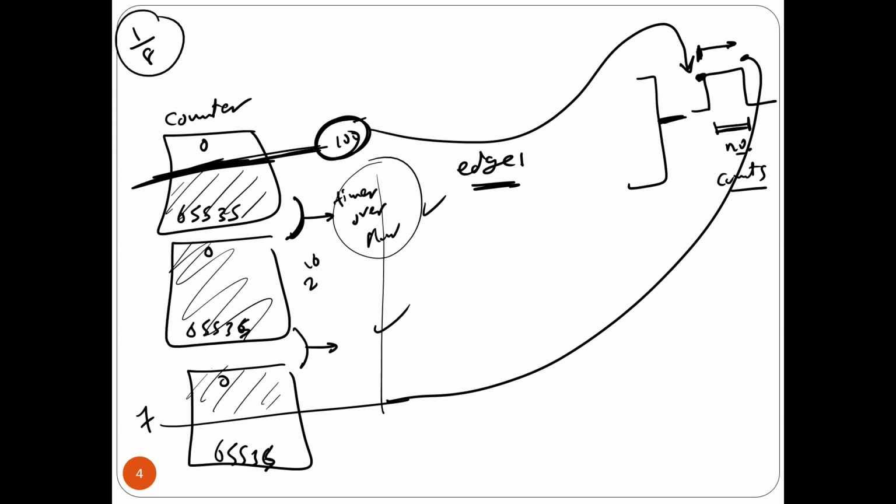That is why, as you will see right now, the timer interrupts are going to be disabled. I'm going to enable them here because I need to count overflows. How many timer overflows from here, starting from this point. Is that okay? Now, so I need 3 numbers: the beginning, the end, and how many overflows. And using these 3 numbers, I'm going to have a formula to compute how many counts you have, okay, as you will see right now.